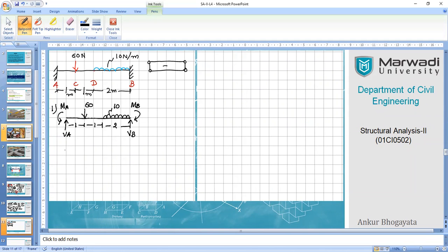All right, so now we are going to use Macaulay's method. Why? Because there are two major reasons. One is that the loading is not symmetrical. Second, it is difficult to develop a superposition of the bending moment diagrams of such complex loading, since the end moments are not symmetrical. Definitely, you will see that the end moments are varying in nature.